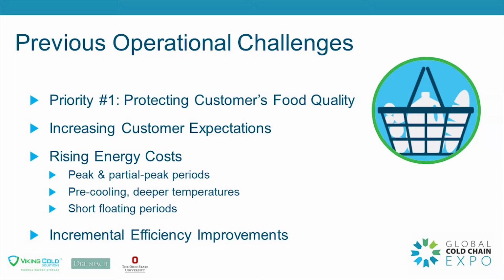Let's start with the premise that floating, which is really the time the product is not operating, the refrigeration system is not operating, takes place all the time through all modalities within the system. Whether it's a temp satisfied within a reefer unit or shutting off for a defrost cycle within the refrigeration unit, we all have a certain amount of float within our operations that we're riding a thermal mass on.